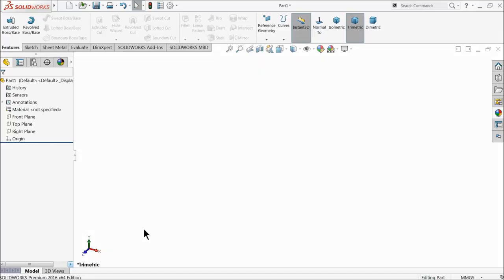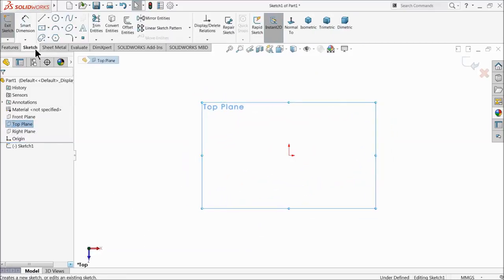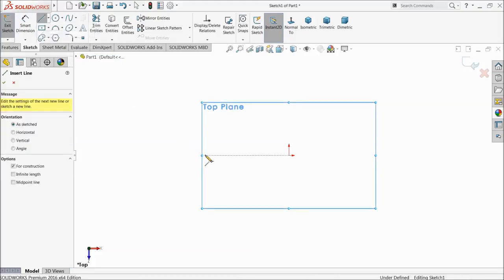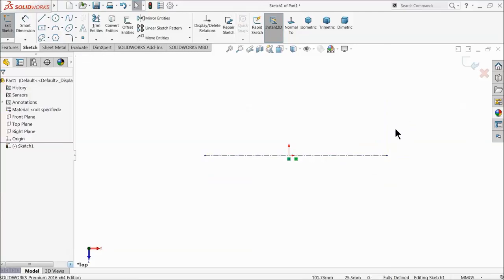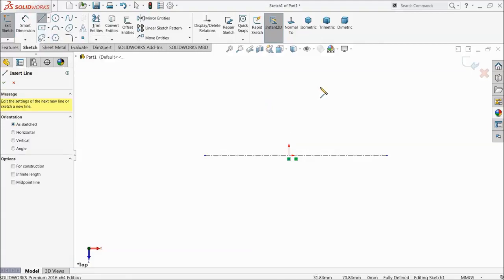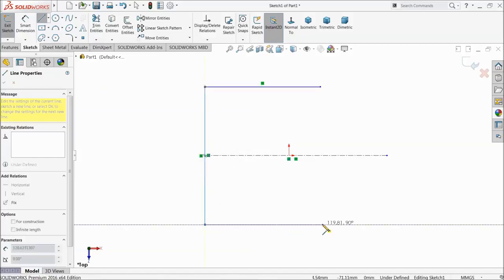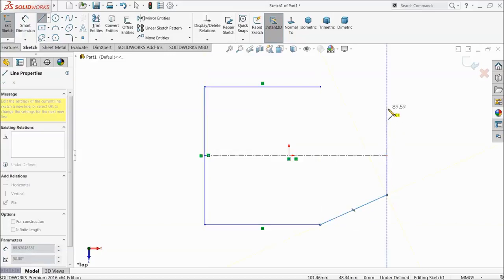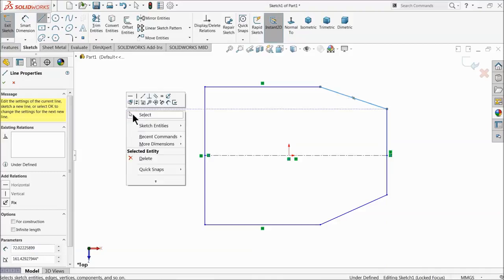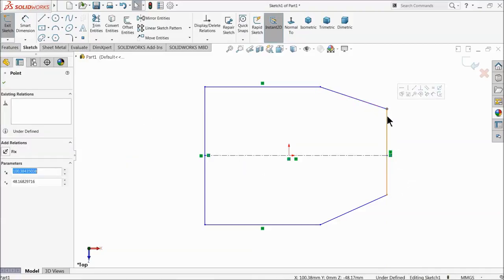Now let's make our first part of the bicycle, the steering. We make a steering handle. So let's start. Top plane, sketch, and here choose. Let us first define a center line. Now then choose line, connect it, exit. Now here let's create some relations.